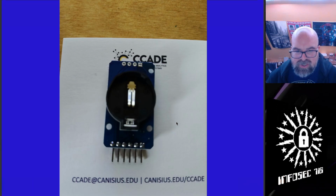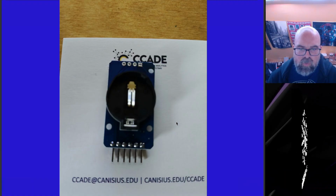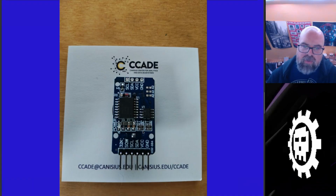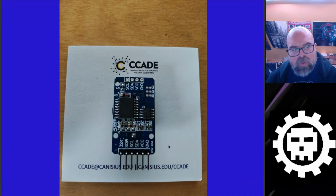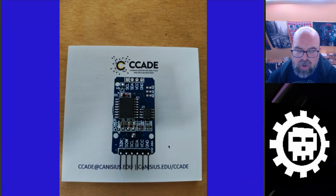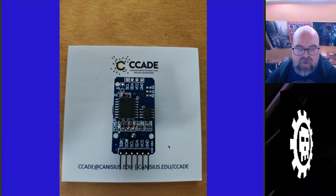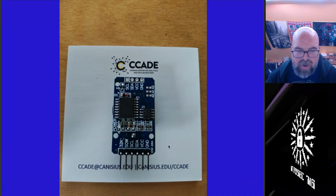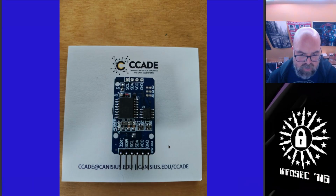One thing that I want to mention, you can use a regular coin battery here, or you can use a lithium rechargeable coin battery. The RTC, when you connect voltage to this VCC pin, can operate on either 3.3 volt or 5 volt input. If you are using a rechargeable, a lithium cell, then you could hook it up to the 5 volt. If you are using an alkaline, a regular non-rechargeable coin battery, you want to hook that up to the 3.3 volt.